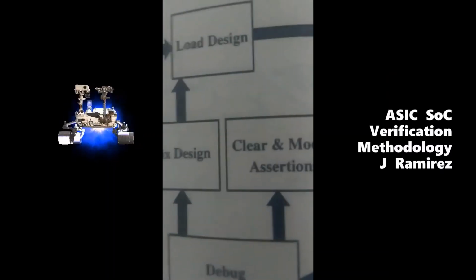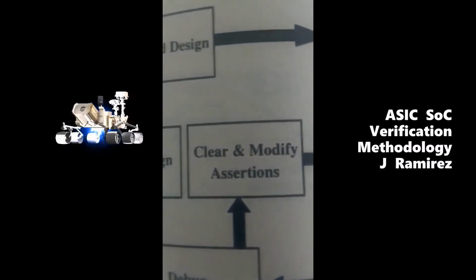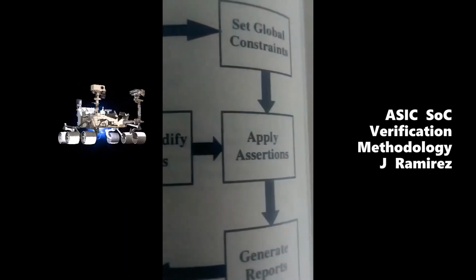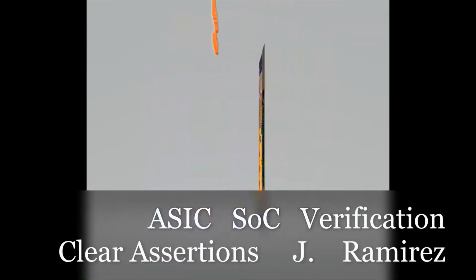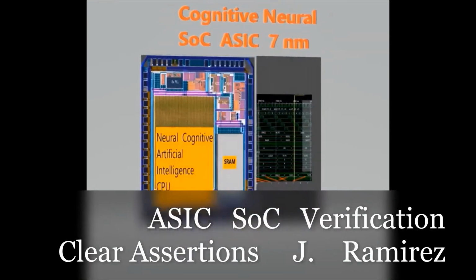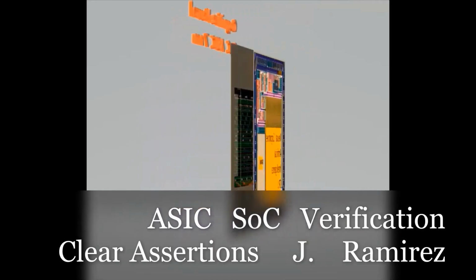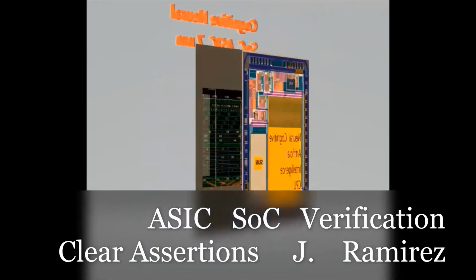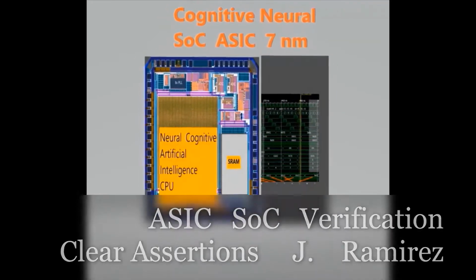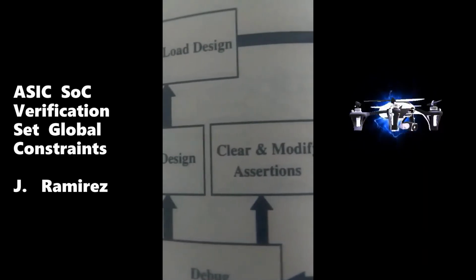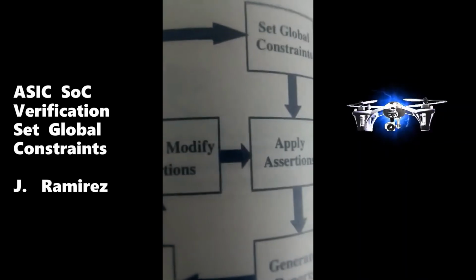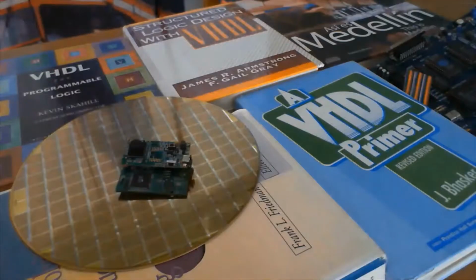As an example, a regular structure such as an adder may be very easy to envision and to lay out, since there is a high degree of parallelism among all of the bits of the adder. So the same adder, when synthesized, may not have this level of parallelism. Each bit can be constructed differently. This places some limits on the ability to do custom layout of synthesized logic.